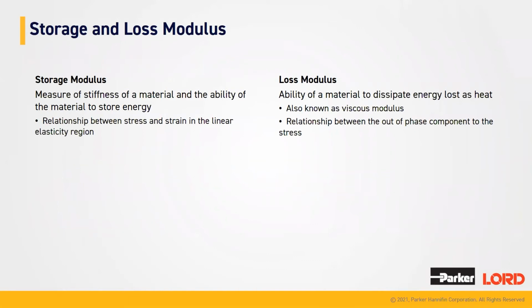Next, on to the storage and loss modulus. Storage modulus is the measurement of the stiffness of a material and the ability of the material to store energy. It's the relationship between the stress and strain in the linear elastic region. And then moving on to the loss modulus. The loss modulus is the ability of a material to dissipate energy as heat. You may or may not have heard of loss modulus before, but the other name that could be more common is the viscous modulus. So you may be familiar with that term. And it's the relationship between the out of phase component of the stress.